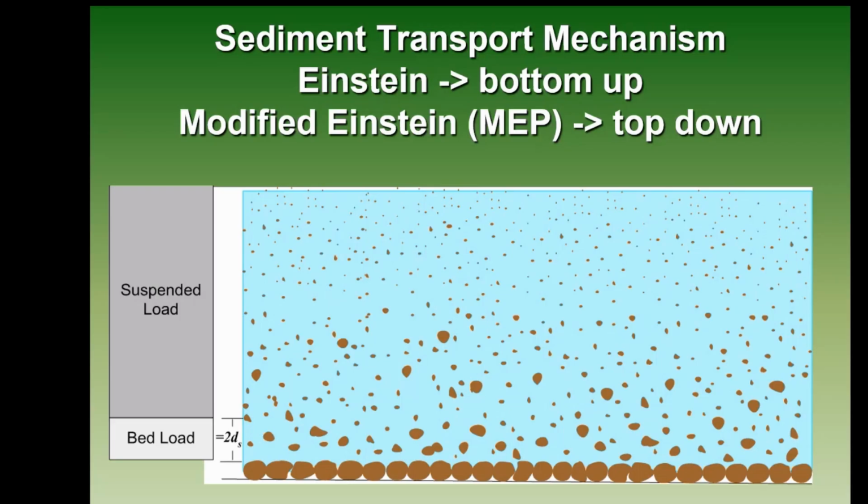It works well for gravel, coarser grain rivers and whatnot, but for sand-bed rivers, it was shown not to work very well. One of the reasons is that you calculate a humongous grain size and concentration near the bed, and you extrapolate this, and you'll be off by 2-3 orders of magnitude, to the point that I remember Jack Kennedy going to a conference, and he said, if you want to predict sediment load, my friend, just predict 0, because you're sure you won't be off by more than 100%. Because if you use any of those methods, you could be off by 1,000%, you know.